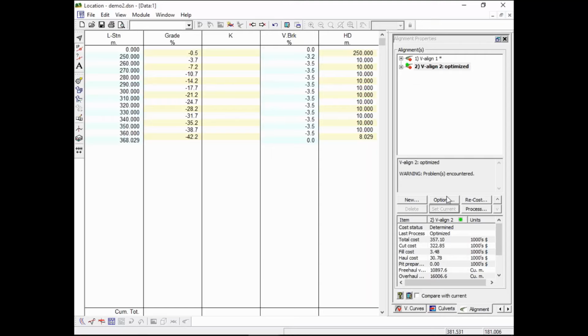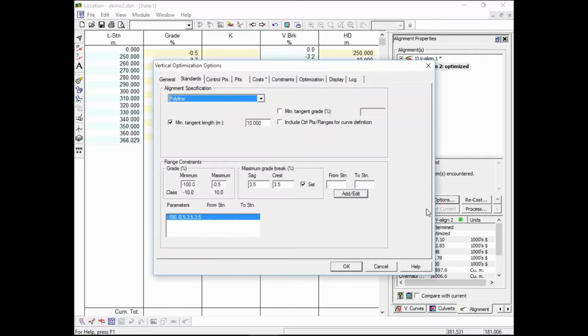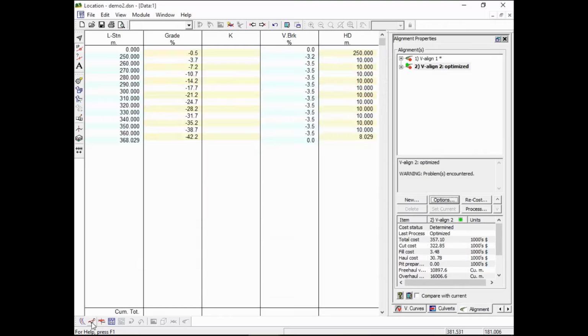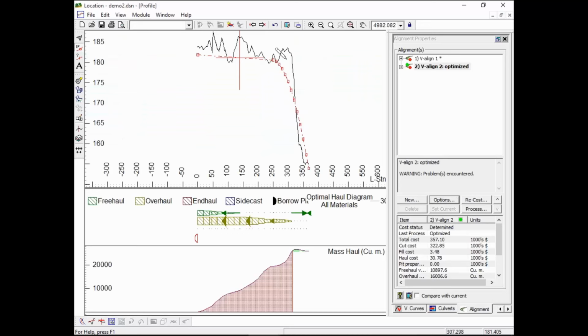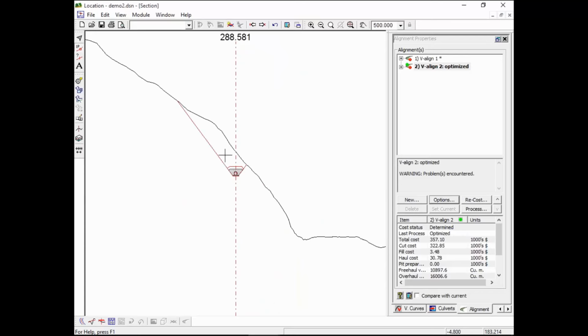Before I carry on, just notice here that under standards, I can put in a station range. So I could actually say, I'm using field bends here everywhere, and I end up with this curve, right? It's a gentle curve. Why don't I put in a factory bend at the corner there at station 292 so that it will not have so much cut in that zone? Because you can see from the cross section there that we're way underground. There's a lot of cut there.